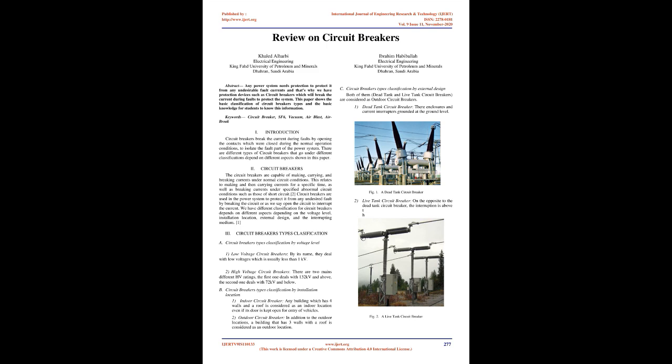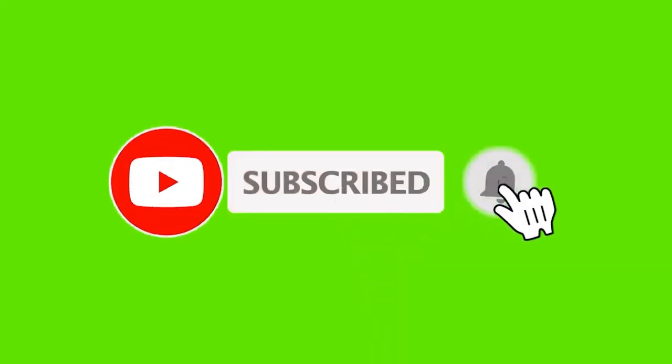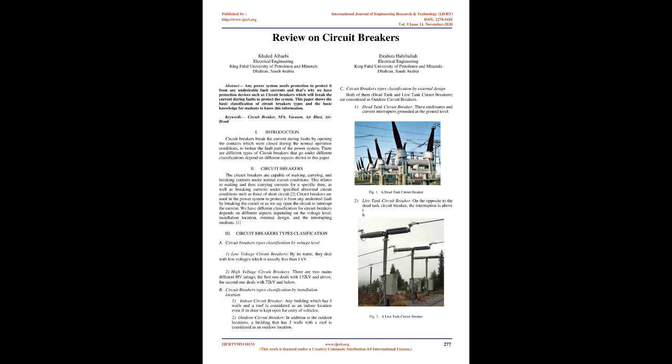2. Circuit breakers. Circuit breakers are capable of making, carrying, and breaking currents under normal circuit conditions. This relates to making and then carrying currents for a specific time, as well as breaking currents under specified abnormal circuit conditions such as those of a short circuit. Circuit breakers are used in the power system to protect it from any undesired fault by breaking the circuit, or as we say, opening the circuit to interrupt the current.